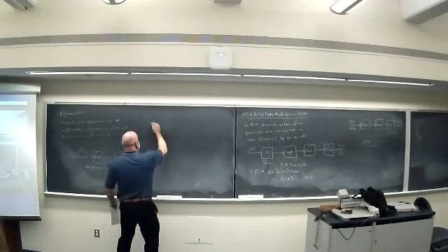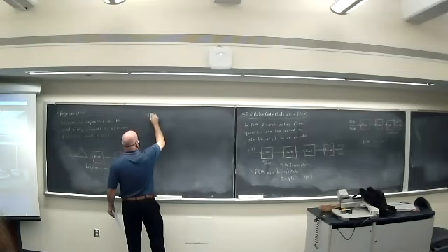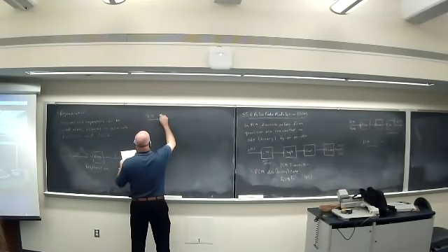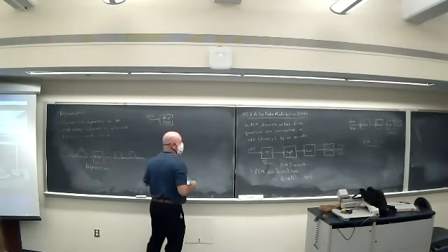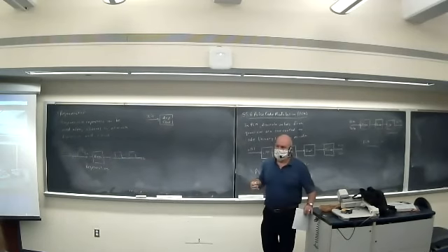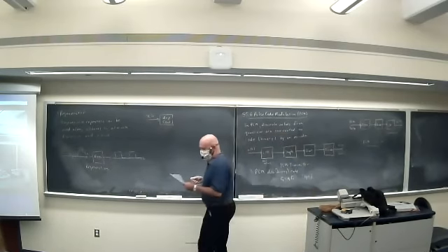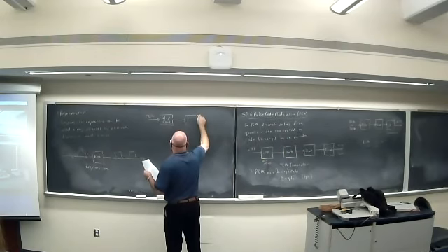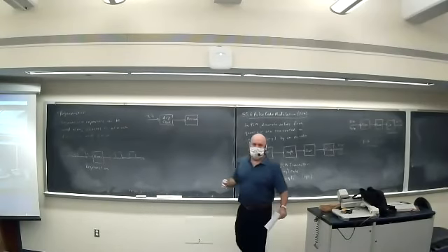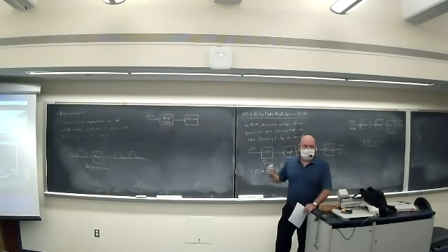Now, the components of the regenerator are: there's typically amplification or maybe some sort of equalization if I know that my channel introduces some sort of distortion. And then the other part of this is I'm just going to write it as a decision circuit. It's usually nothing more than a comparator.